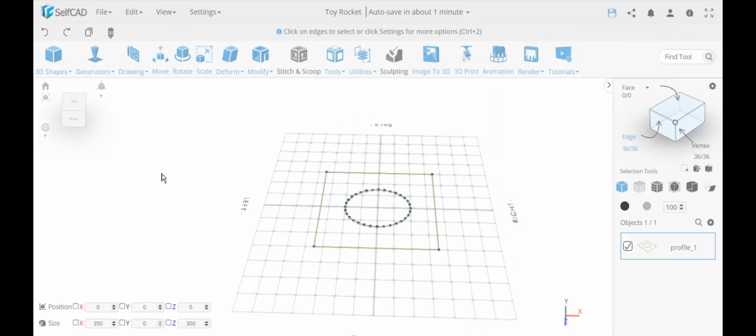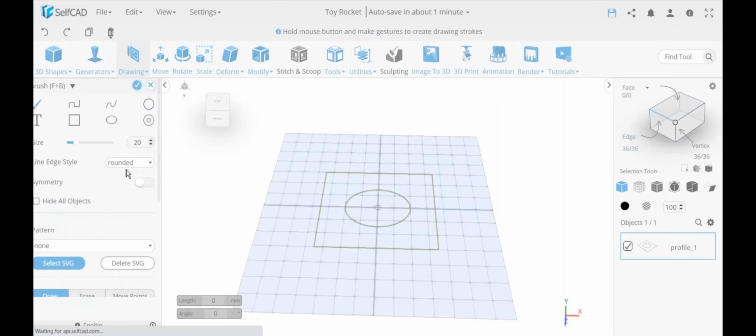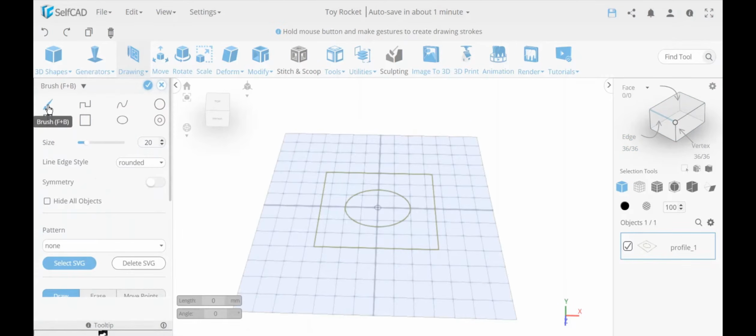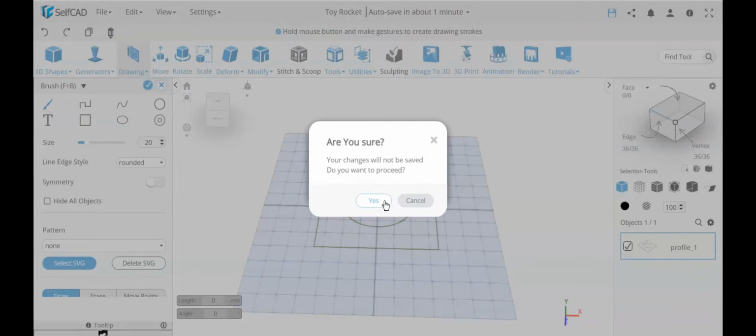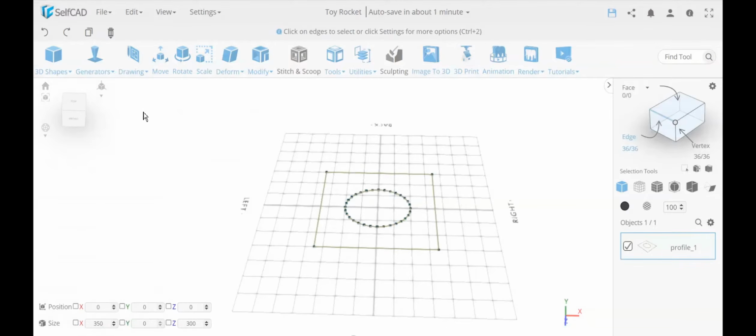Okay, so now what I discussed in the first example is that we use the brush mode over here, the brush, when you want to get the exact thickness, like the thickness of a wall or something like that. There's also an option to use quads. If you want to draw here with the wall thickness, I can basically use rectangles and draw it like this, with exact measurements.